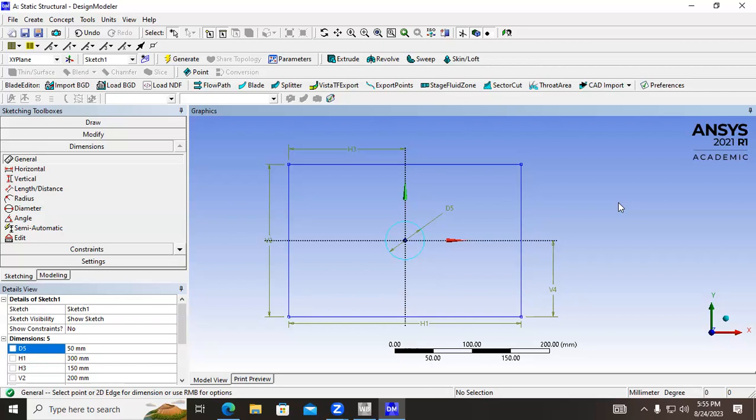Okay. All right, so we're just about done here. The last thing we have to do is turn this into a surface. You can almost think of this as kind of extruding it. We're not really extruding it because we're doing a 2D simulation, but we have to let Ansys know that we don't just have a sketch here, we have an actual solid.